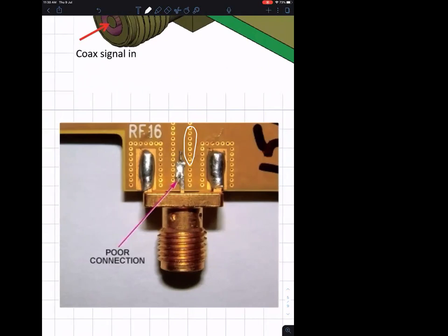So to make the ground equal potential, let's say you have a ground, you have a device here. For example, you have a device here, and then you have a device here, and this is grounded here, and this is grounded here. If they don't have a very good common ground, then they're going to have some kind of voltage drop across here.